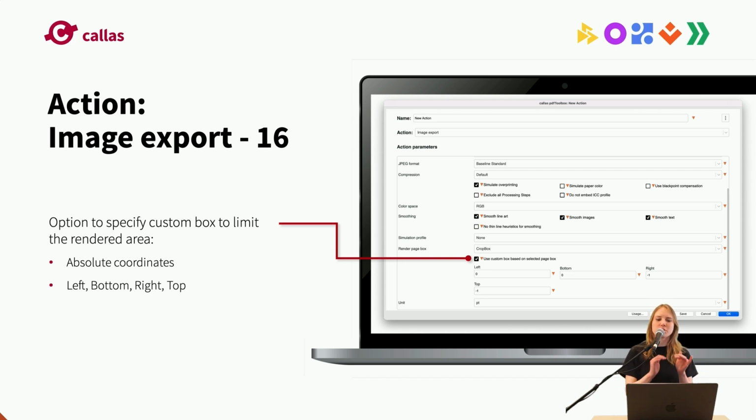So for example, if you just want to export a specific area of your PDF page, then you can specify that here using absolute coordinates, meaning you have to specify the left bottom as a start point and the right top as an endpoint of the custom area. And that sometimes could be a little bit tricky and is not always so easy to set up.